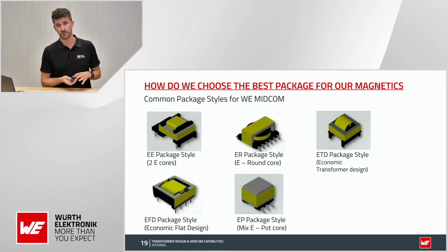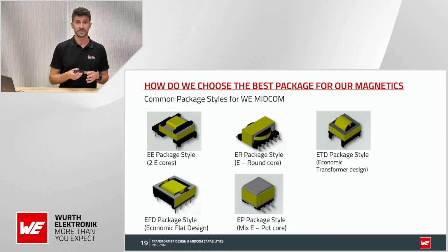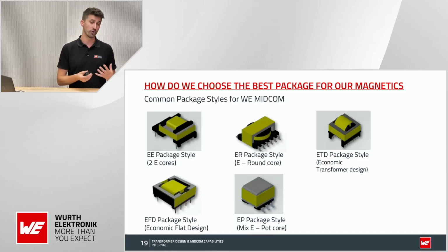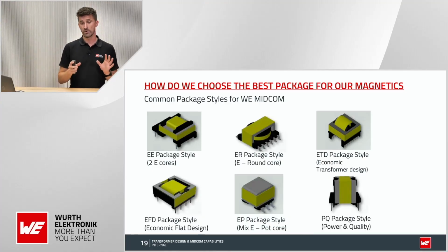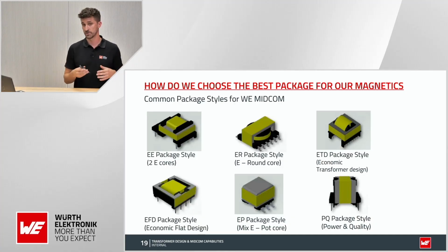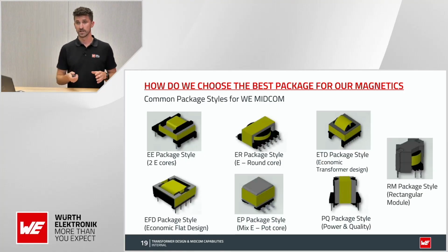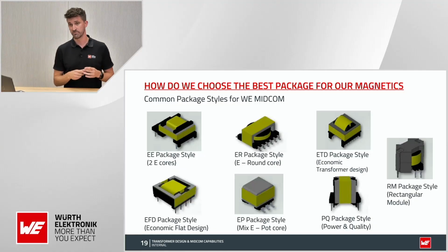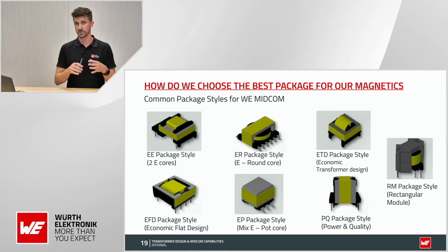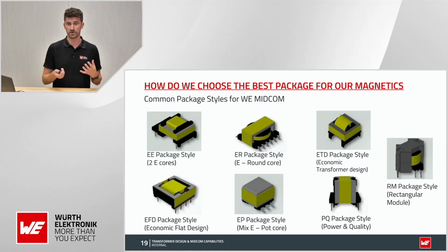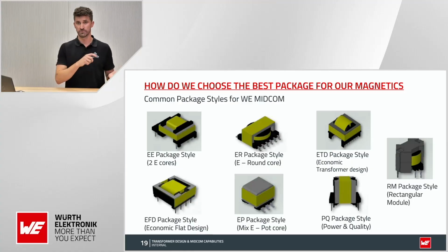What we can see here is one of the biggest packages in our portfolio, an ETD package style, which stands for Economic Transformer Design. And now, in the same power range, we are seeing a PQ package. This package is very common in inductors and PFC, and probably that's why it was named after power and quality. And then one last package that remains in the same family is the RM package, which is called like this because it's a rectangular module. And it is one of the best packages we have in terms of ratio between volume and power density.